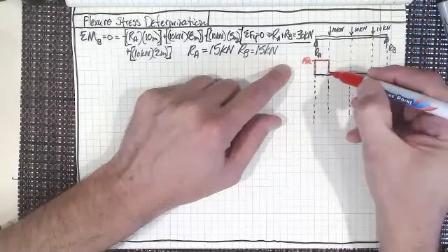So when we do it, the first thing is 30 kilonewton meters. So we know that we have to be up to 30 kilonewton meters, right? We're going up here because we're coming from 0. We have to have 0 at both ends. So we're going up. That's positive slope, right? So positive slope of 30 kilonewton meters. How many meters am I going?